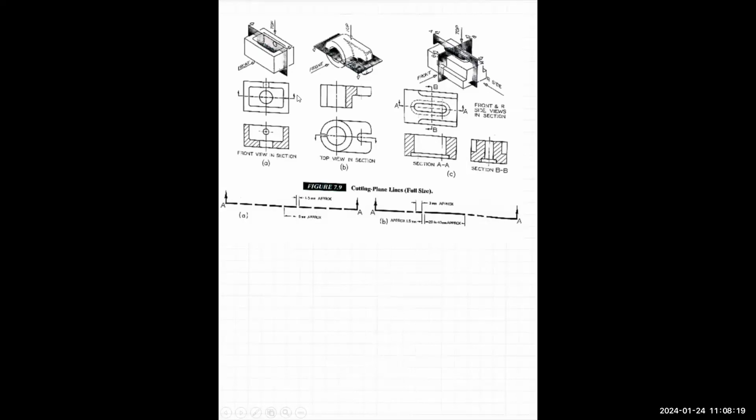The arrows refer to the view position. So it's like, okay, the view is this way. The arrows are showing you which way the view is. And that's the section that's associated with this cut. Okay, and the section is drawn instead of the front view. That's pretty common. The front view is just a rectangle, right? Not that helpful with a bunch of hidden lines back behind it. So instead they cut it and draw the section. There's no hidden lines. Everything can be dimensioned.